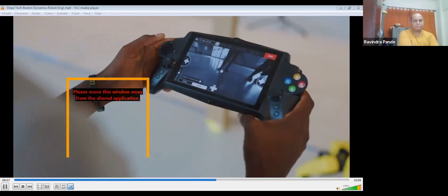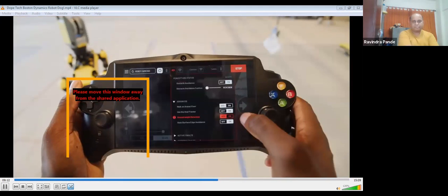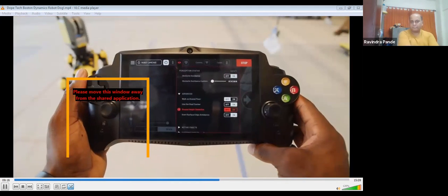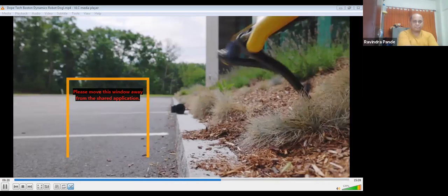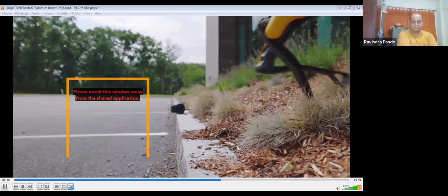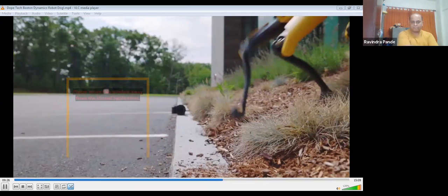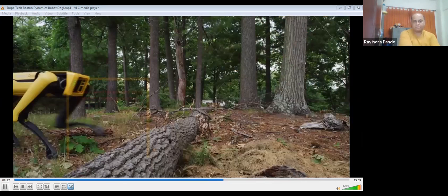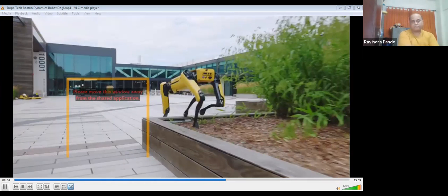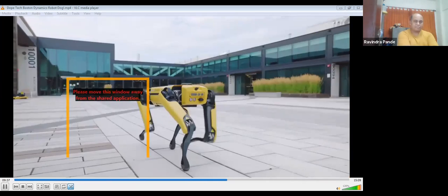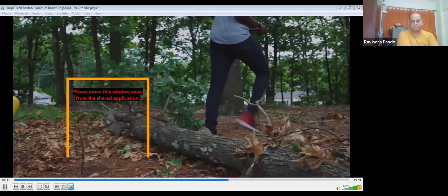And the ground height detection is important too. It's always mapping what's in front and the height of what your next step should be. So with that feature turned off, you can actually see it walking into a curb, and it kind of trips its way onto the higher ground before correcting itself. But with that feature on, it already knows to take a higher step when there's a curb in front of it. It doesn't trip at all. And if there's ever an obstacle in front of it, it's mapped out the whole thing, and it already knows how high each step should be to climb over something, like a real dog would know if it was walking over the same thing.